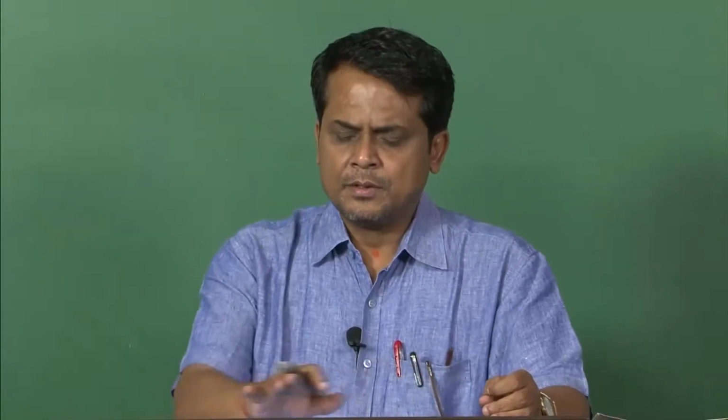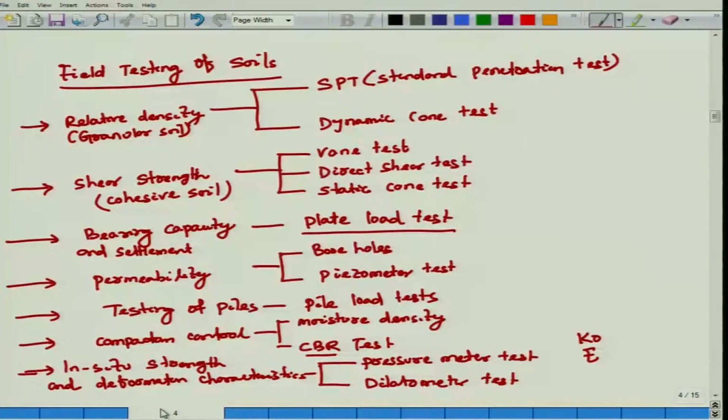So, these tests in brief, because this is foundation design, and unless you know these parameters, you have to recommend as a geotechnical engineer: okay fine, I will go for one borehole, I will collect soil sample below 10 meter, at the same time I will do one field test, standard penetration test. It gives me penetration value.